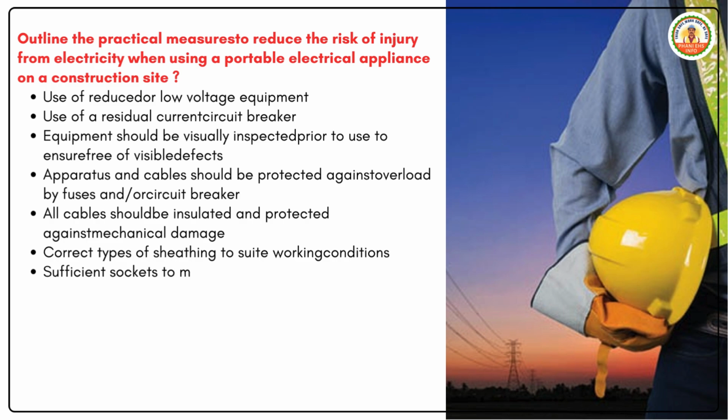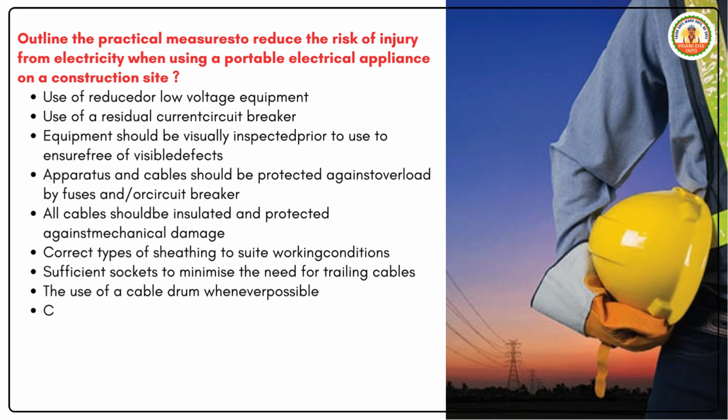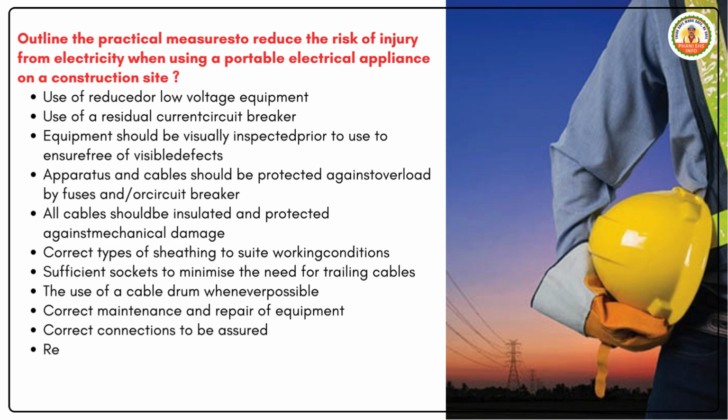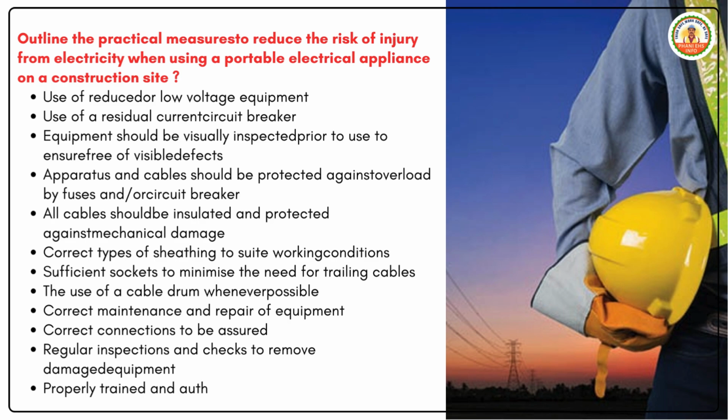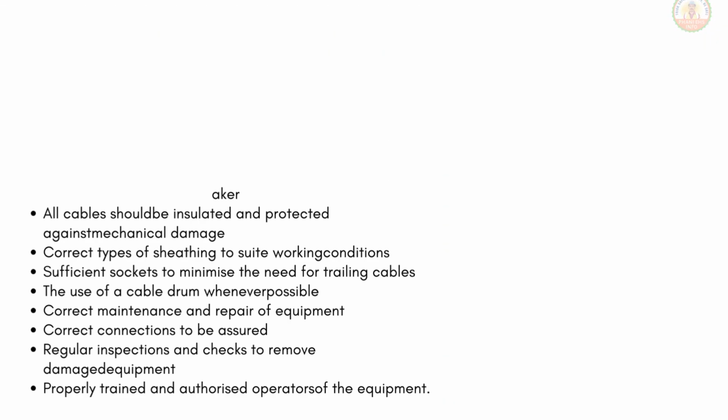Sufficient sockets to minimize the need for trailing cables. The use of a cable drum whenever possible. Correct maintenance and repair of equipment. Correct connections to be assured. Regular inspections and checks to remove damaged equipment. Properly trained and authorized operators of the equipment.